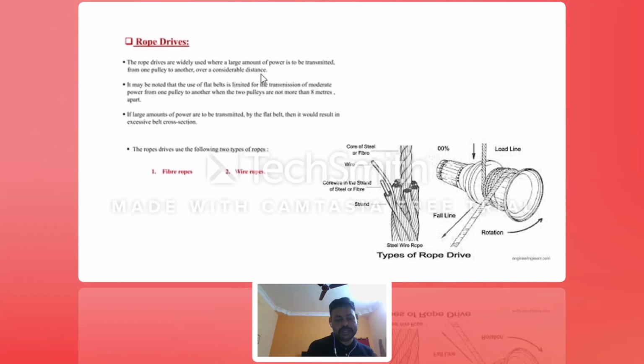So I could remember my school days, almost 30, 35 feet, we will get the water level. We will tie a bucket into the rope and put it into the well. Then finally, if you are pulling without a pulley, it is very difficult to pull the water, and at the same time the rope will tear. Whereas if you are using this pulley setup, the effort will be reduced, the rope life will be more, and you can smoothly take the water out from the well.